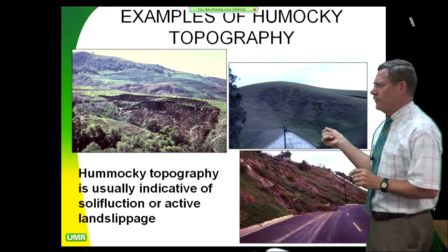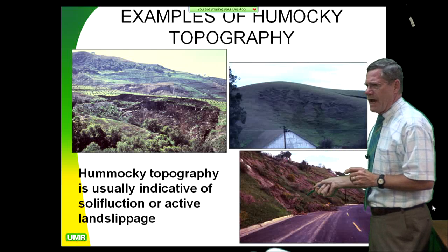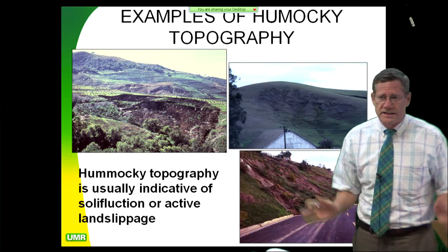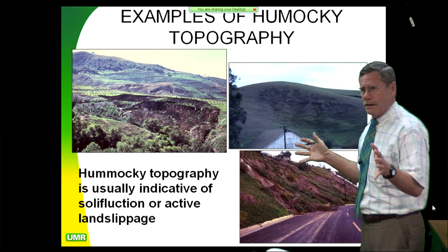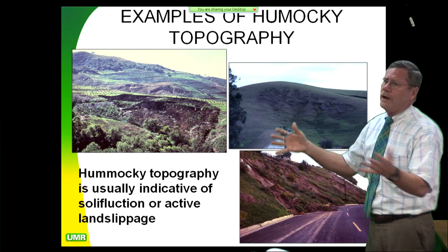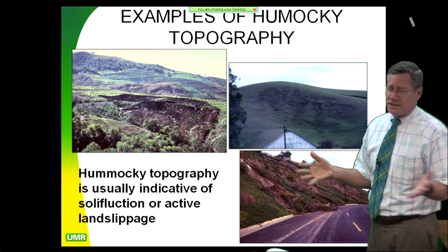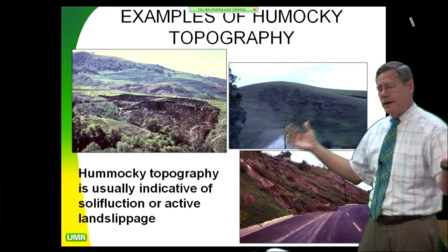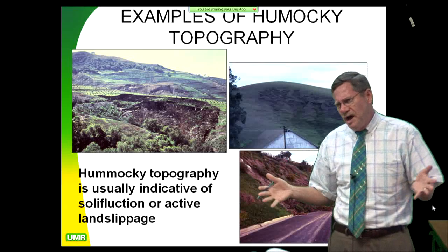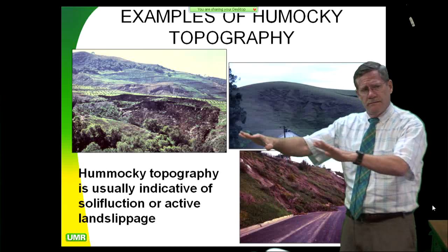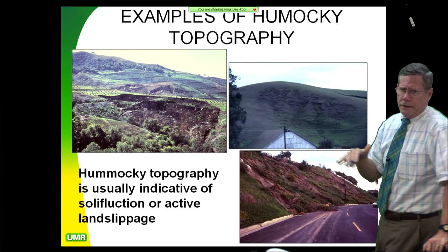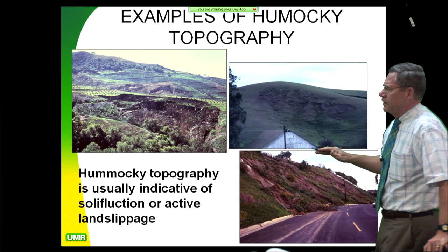But what's really critical for landslides is a ½ inch a day drizzle over 21 out of 30 days. That's going to put more volume of water into the ground. You start getting more than ½ inch a day, you're overwhelming the system. And so a lot of it's going to run off. So when you have a big, huge storm that comes through, dumps a lot of water, you get a lot of flooding, but it doesn't cause deep-seated landslides. That's an accretion of groundwater seepage that causes big landslides.